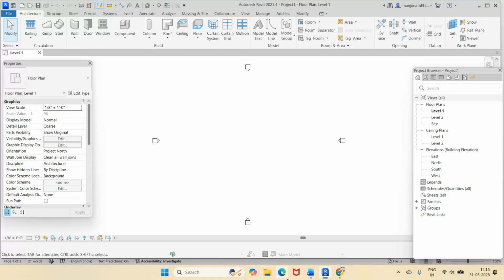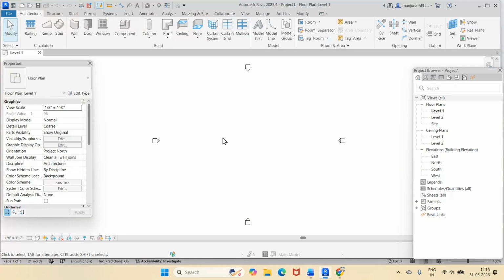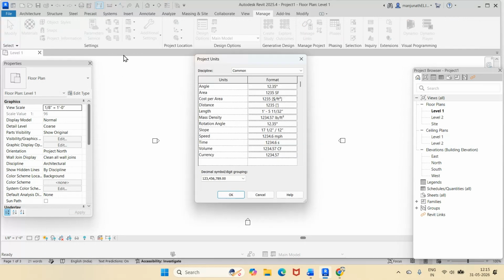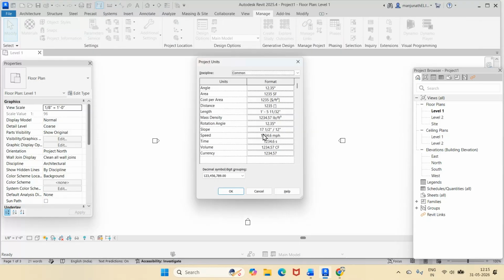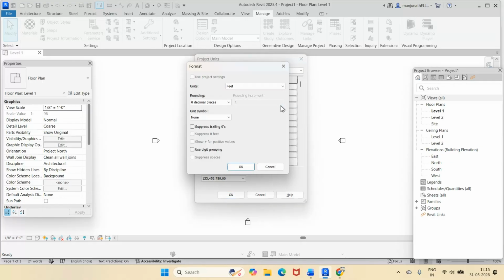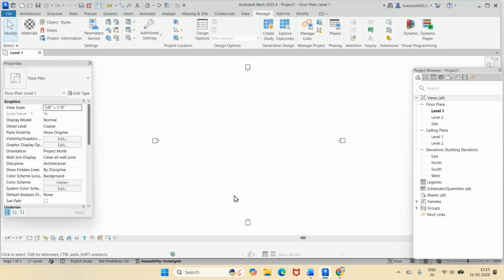So first thing is here all the dimensions are given in feet. So I will just select the template drawing as the default imperial. Then first I want to go for the setting. So to do that, first I will go for manage, then come down to units. This is one method, or else I will just type UN directly. That is the shortcut key. In this, I want to go for the distance. You just click on this and make sure that you have it in feet. And I will say OK. And then I will take up the OK here. So now we have set the units.